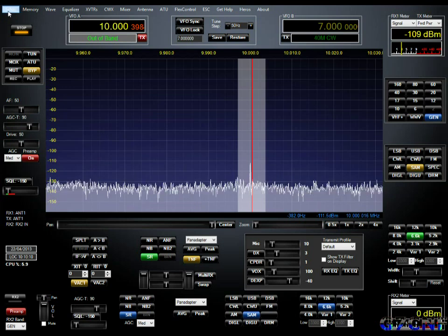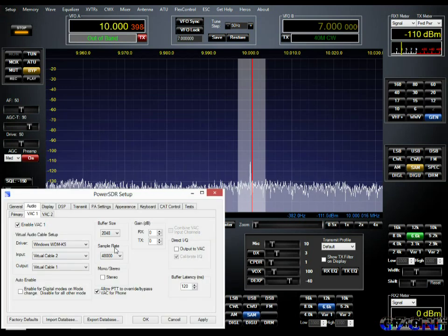Going back to our setups. So now we have sound coming out for our sound card programs. A little bit further down the line, you can actually output the I over Q to a VAC, and in fact it would be possible to run another SDR program like Simon Brown's SDR-radio, for example, and output the I over Q to that and implement further receivers from inside the current bandwidth of your radio, which is quite interesting, but something we're going to leave well alone.